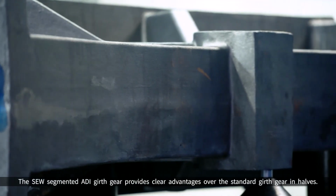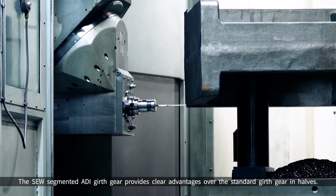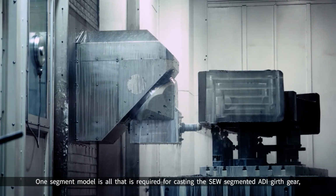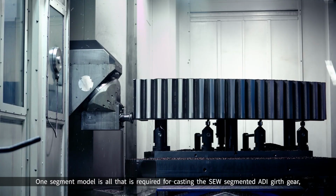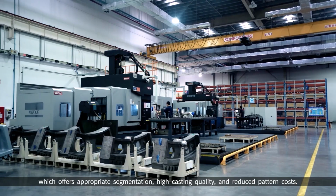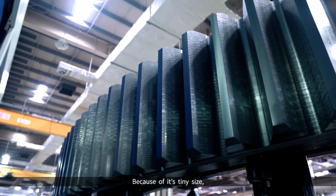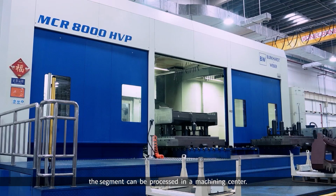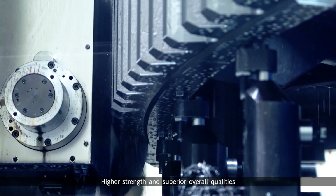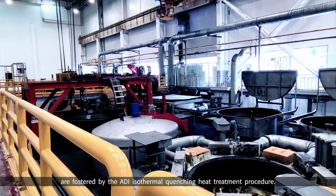The SEW segmented ADI girth gear provides clear advantages over the standard girth gear in halves. One segment model is all that is required for casting the SEW segmented ADI girth gear, which offers appropriate segmentation, high casting quality, and reduced pattern costs. Because of its tiny size, the segment can be processed in a machining center. Higher strength and superior overall qualities are fostered by the ADI isothermal quenching heat treatment procedure.